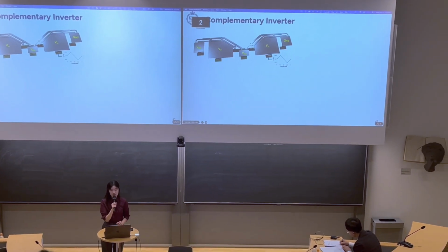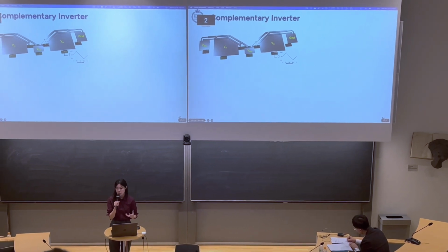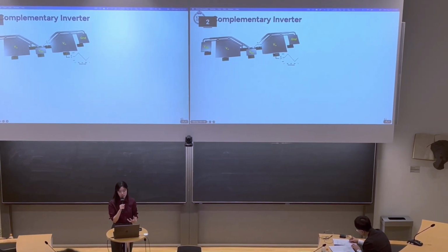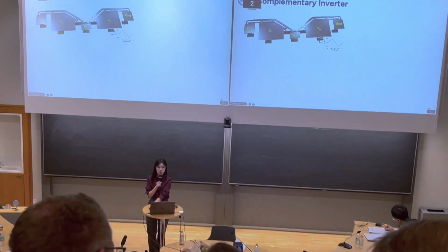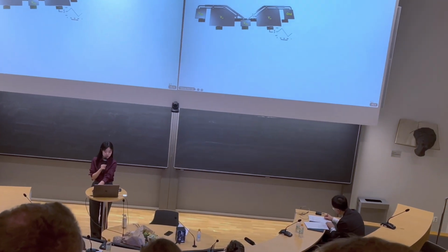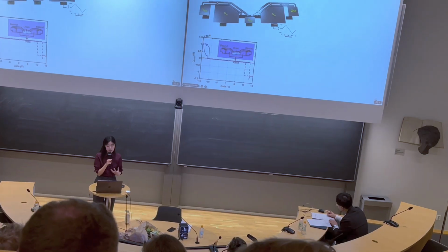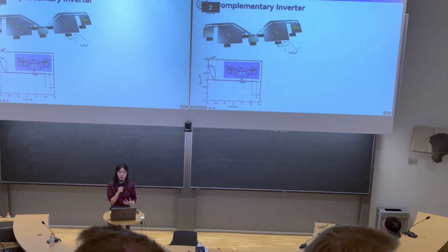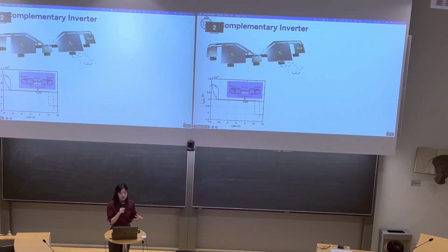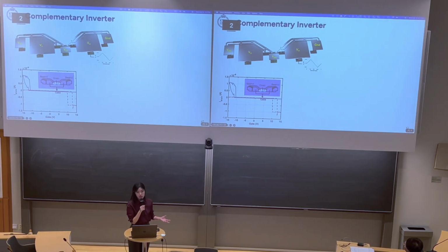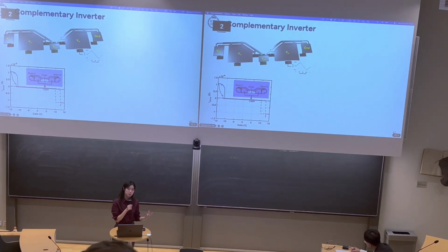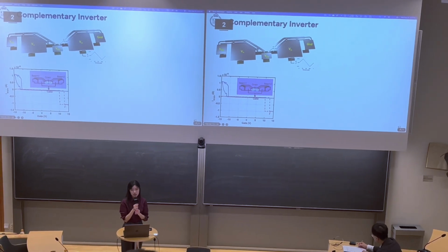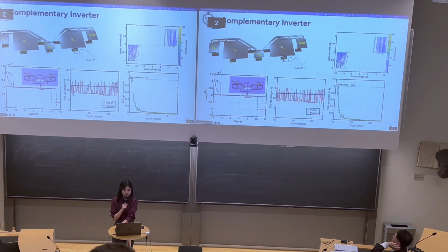And next, this is the first integrated circuit we implemented with the 3D integration approach. The complementary inverter is the most foundational logic demonstration, and we implemented it here with only 2 3T NEM switches. Since the NEM switch is polarity independent, there are no N-type or P-type devices. One and the same device can work as both pull-up and pull-down switch, depending on how it is biased.